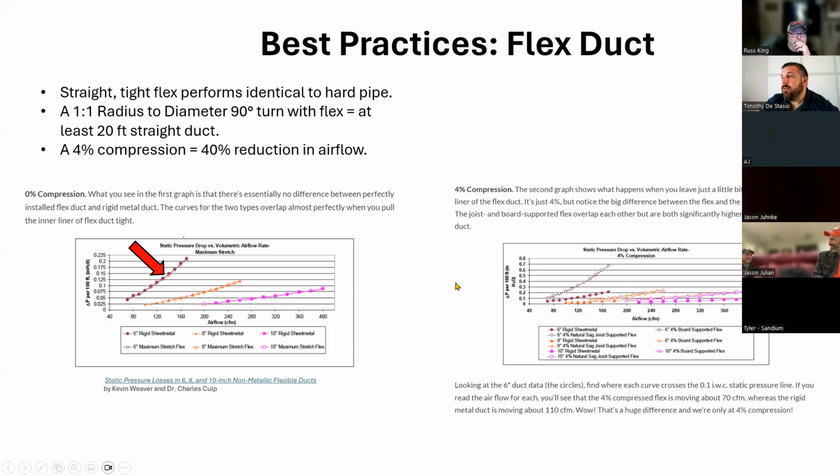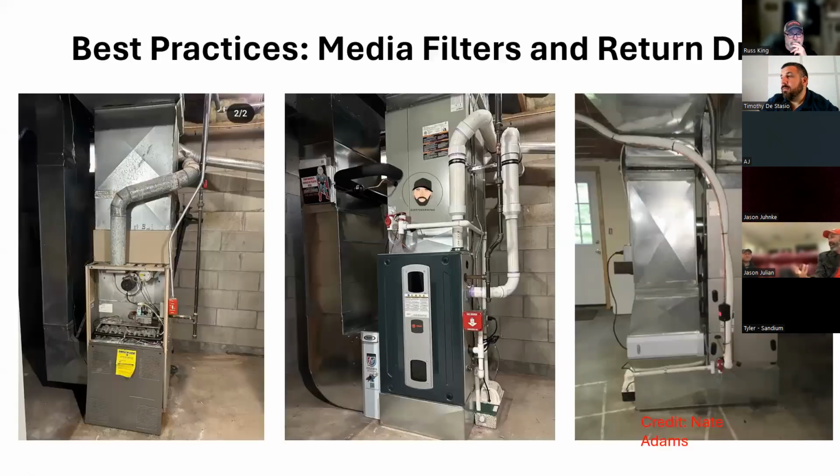Use metal 90s to make your turns. Only run flex straight, pull tight, no sags.